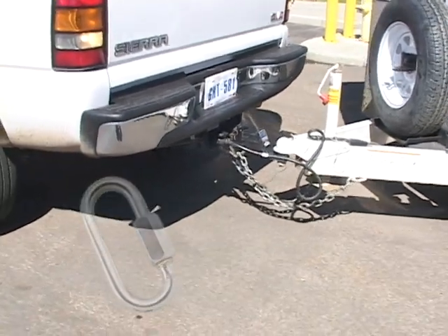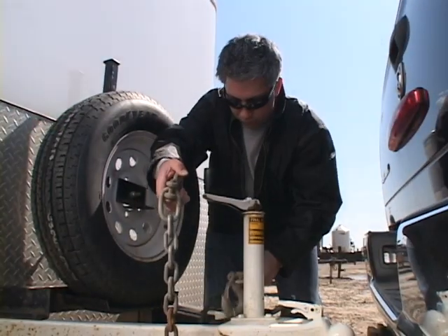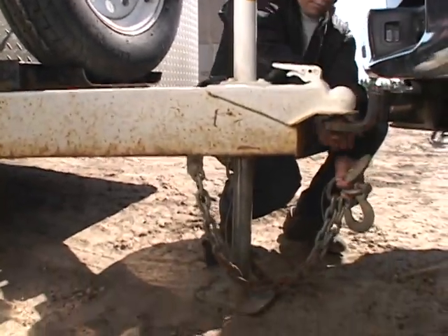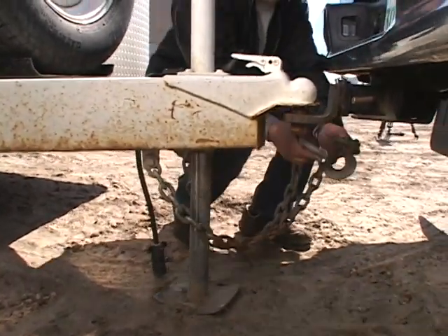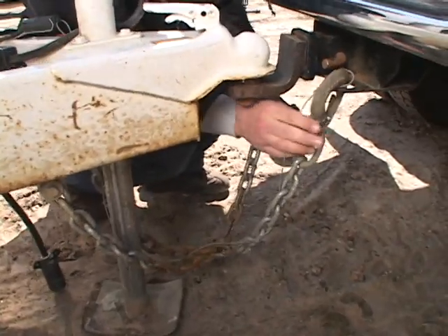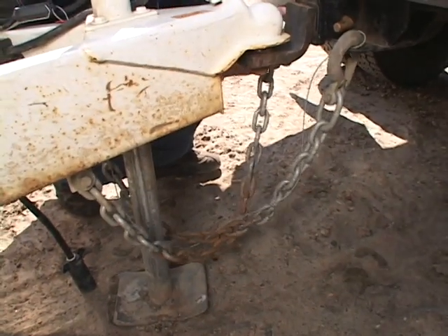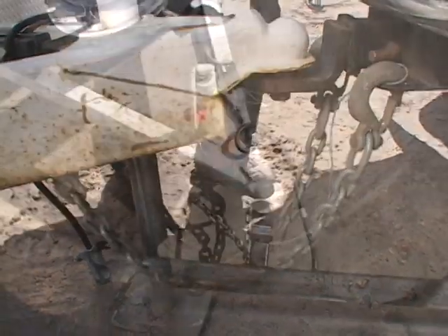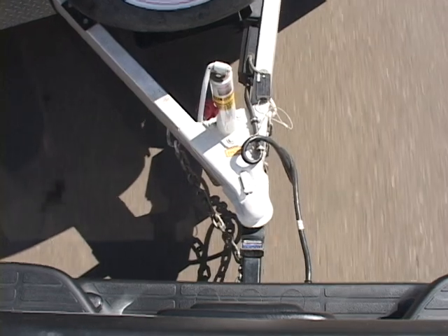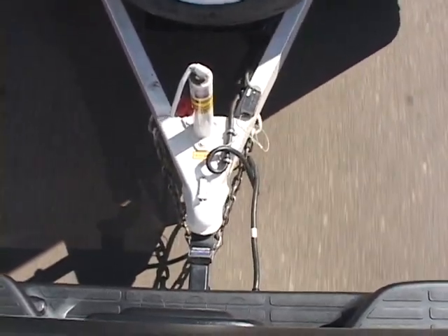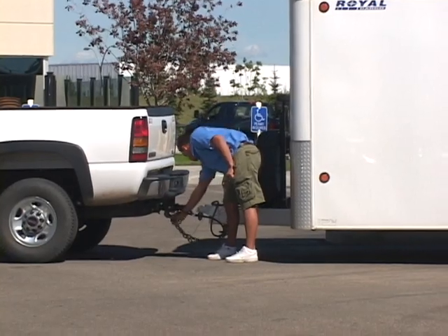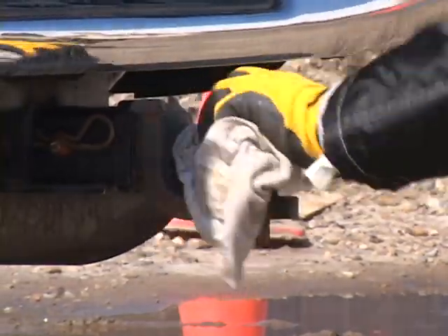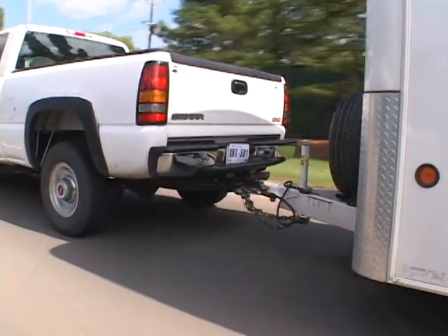When attaching a trailer to any vehicle, make sure it is hitched securely. The trailer tongue should be snug on the ball when locked. To prevent the tongue from dropping to the road if the primary hitch accidentally disconnects, chains should always be crossed under the tongue. They should not touch the ground, but they must be long enough to allow the trailer to turn corners without any restriction. Check to ensure all hitch and coupler components are secure. The connection point may require periodic lubrication to permit free movement of the coupler on the hitch ball.